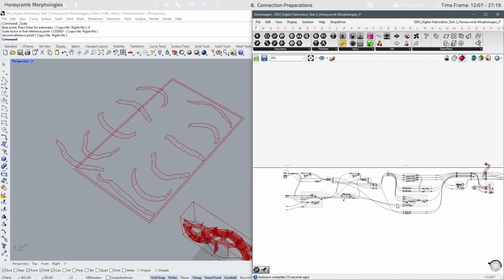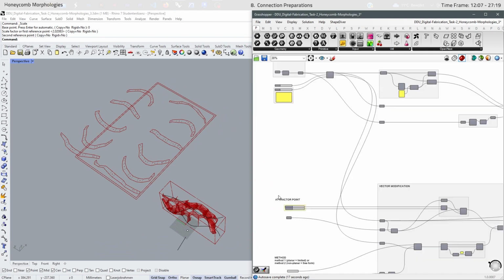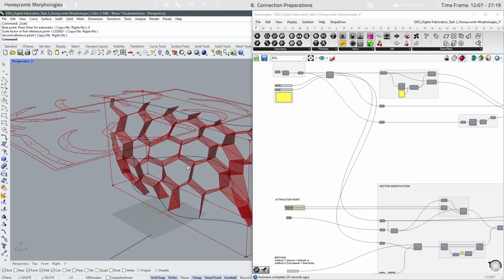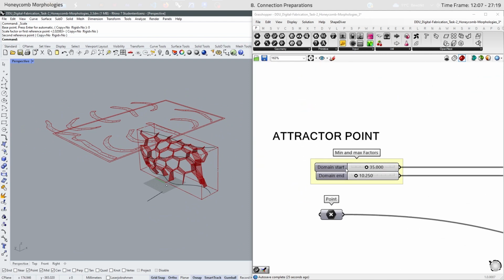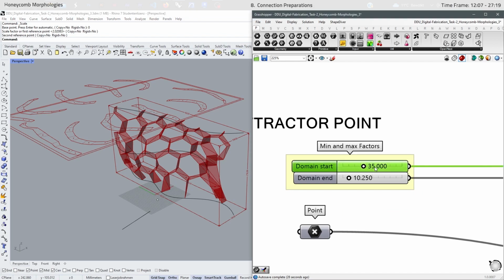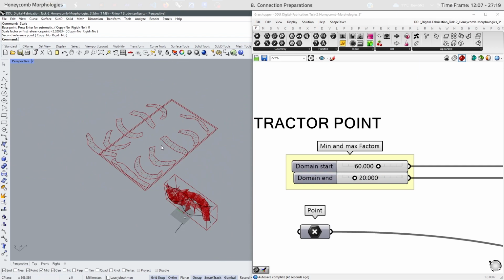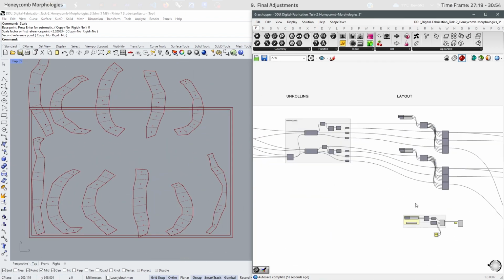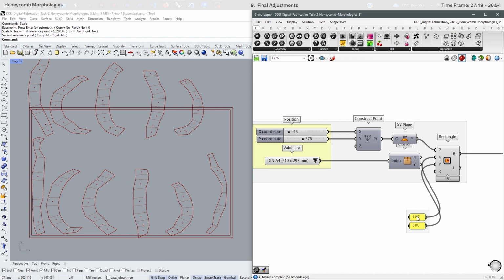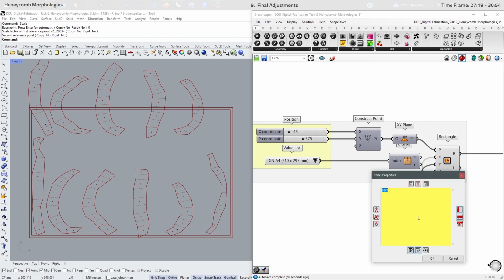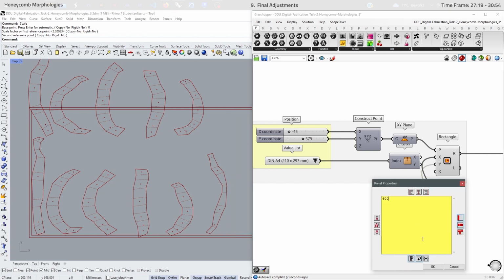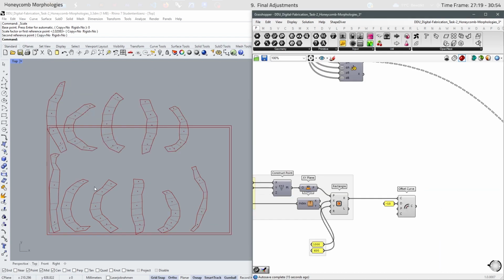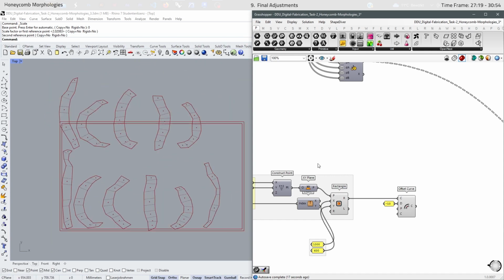And when we are scaling the geometry, we also have to adjust the component depth. So we can do this at the beginning, here at our settings for the attractor point, and increase these values. I also adjust these values for the laser cutter at TU Darmstadt, which is 1000 by 600. Then we will bake it and bring them closer together.